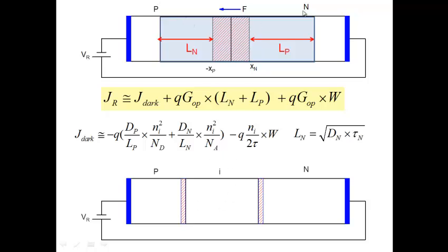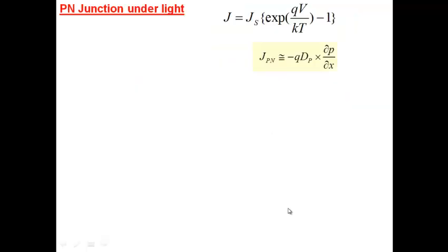All of you rightly said that in the P and N regions, you reduce the doping. So we have done that to the extreme case where we made the doping equal to 0 in this particular region. Okay. So PIN photodiodes are very, very common and widely used here. All right.